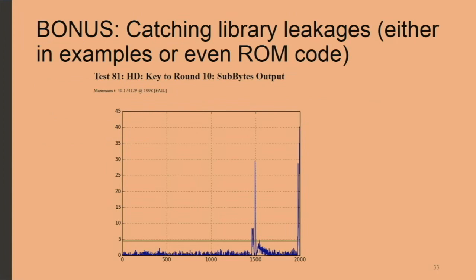One of the other things that occasionally caught this tool is you could see stuff like ROM code. So some devices have ROM code that calls the hardware accelerator, or they provide a library that most people are using for talking to the hardware accelerator. And you can have issues like if you store the key in a register and you overwrite that key with controlled data, so either ciphertext that's known or the plaintext or something like that, this gives you leakage that could actually be exploited.